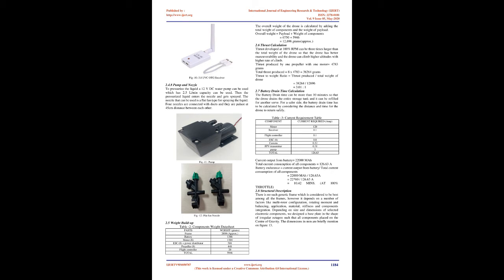2.4.6 Radio transmitter and receiver. The transmitter and receiver used are FlySky CT6B 2.4 GHz 6CH and FSR6B respectively. This combination provides a range of about 1000 meters. This transmitter and receiver provide up to 6 channel options. Fig-7. FlySky CT6B 2.4 GHz 6CH transmitter and FSR6B receiver.